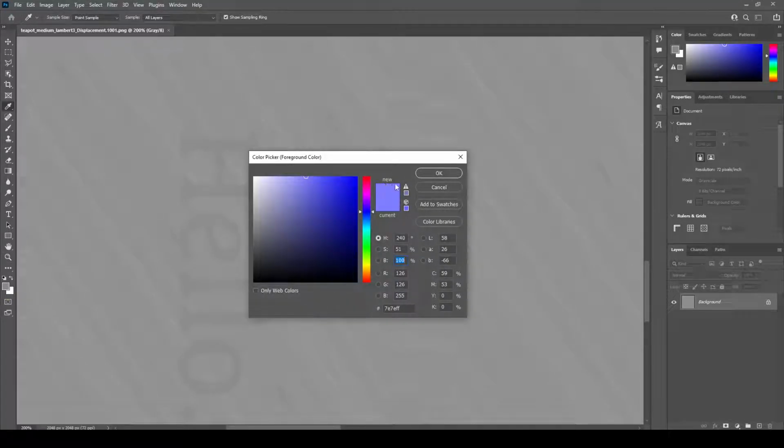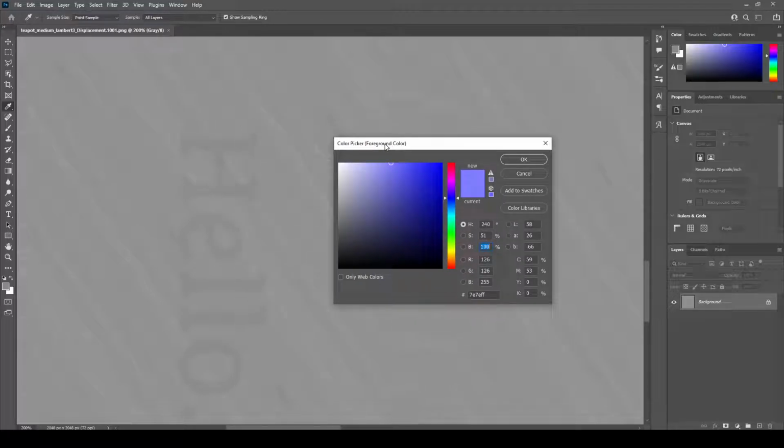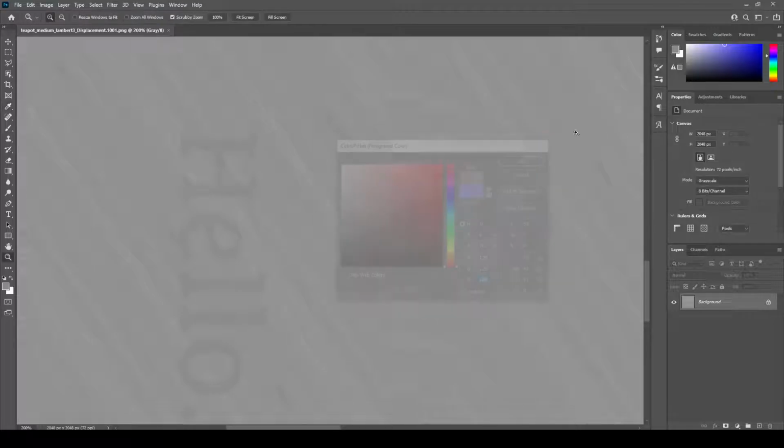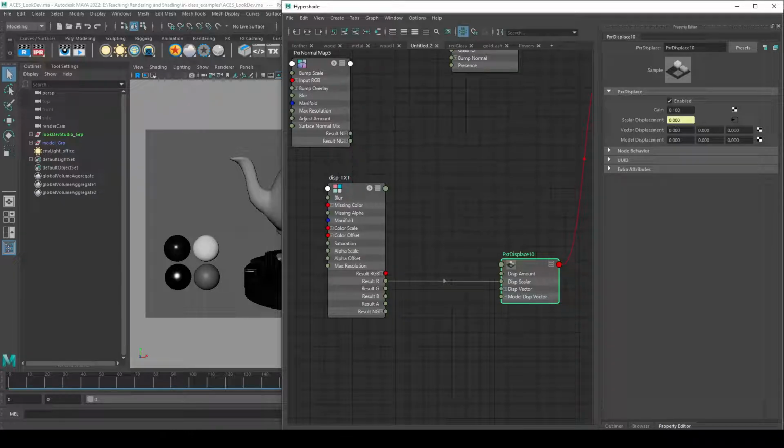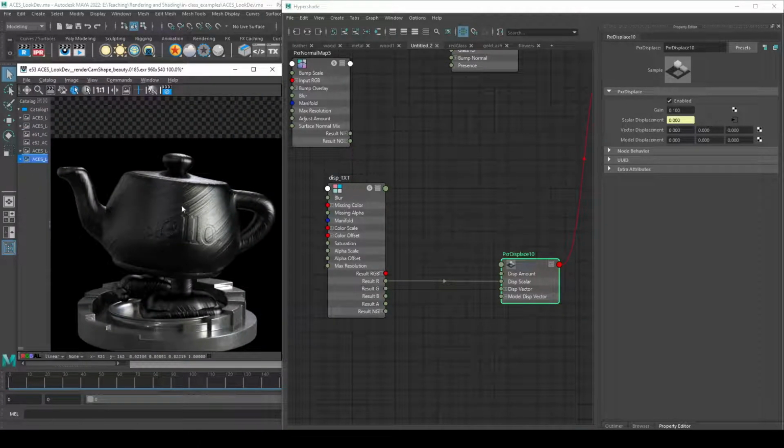This is pretty common amongst displacement maps. This is what's called a gray-centered or 50% centered displacement map. What this does is it's actually treating 50% gray as the middle. If I color select here on a gray value, we're going to get in the 50% range right here. 50% is going to be about, I think 128, is that it? 128, right? So the pixel value is 128, so that's perfectly 50% between 0 and 100%. So that is what this texture map thinks is the flat surface, 50% gray. But clearly, RenderMan thinks that's not true, which is why we're getting that goofy looking inflating teapot.